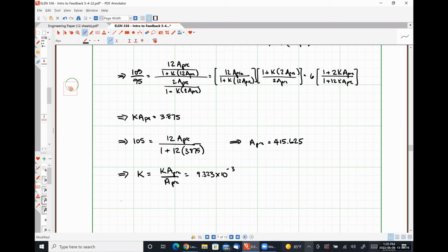So the ratio remains constant while the individual resistor values can go up or down with temperature fluctuations. Right? So that's how we're able to achieve this type of stability using resistors that are inherently dependent on things like temperature and process variation as well.